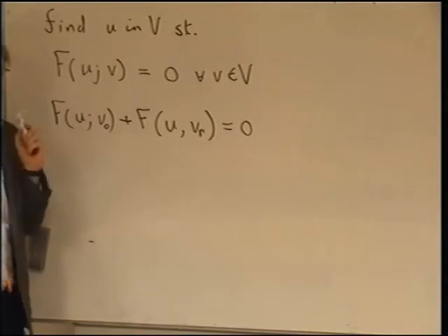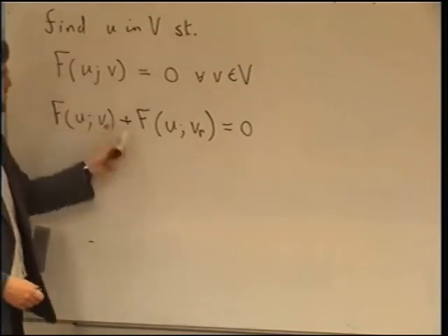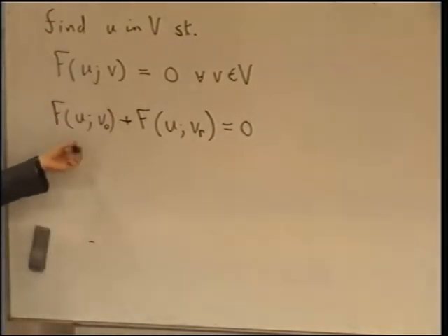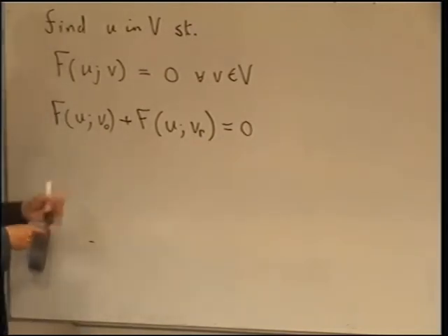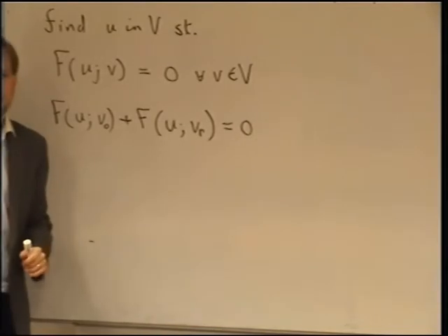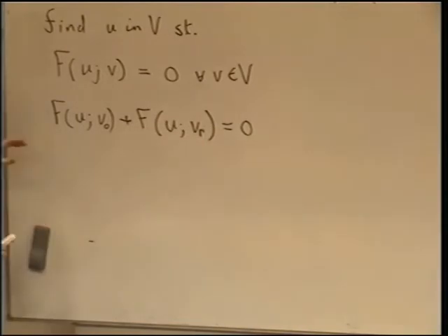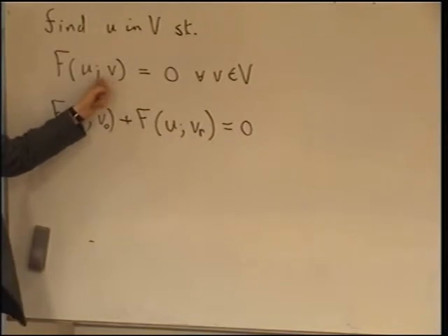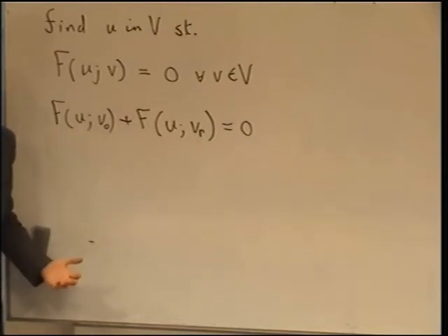Okay, so I couldn't have, in the general case, split U up like this, because if f is not linear in U, then that transformation isn't true, right? That transformation is inherently what linearity means. But because f is linear in V, I can split that part up. And in terms of the practice of the finite element method, what does this mean? Well, remember that what we actually do is we solve this equation for each basis function of V, right? We do this for all the phi's in that position, and we use the linearity to say, well, if we got it for all the phi's, then we get it for all the other cases.